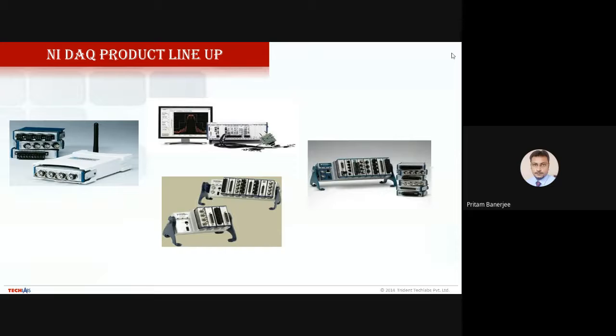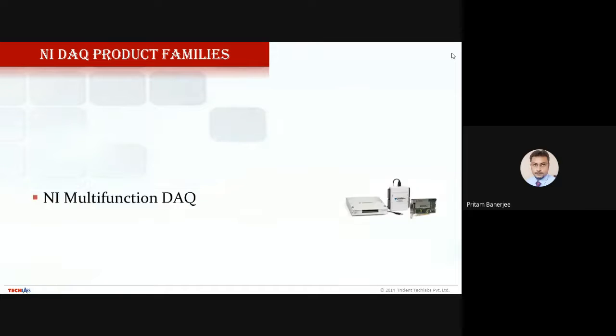So why take a complex data acquisition card? A simple data acquisition card will be sufficient. But if my work is complex, because I want to acquire, suppose, 20 signals, then your data acquisition card might have 20 channels to take as input. So depending upon that, your data acquisition card will also vary.